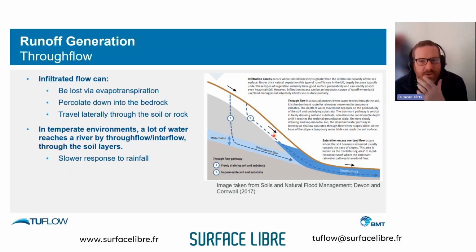No. If you're doing percentage-wise, the impervious fraction will impact the amount of infiltration that can occur through one of the soil infiltration models. So it's not just a fixed percentage, it would be a fixed percentage of the continuing loss, for instance, or a fixed percentage of the Green-Ampt or the Horton infiltration.